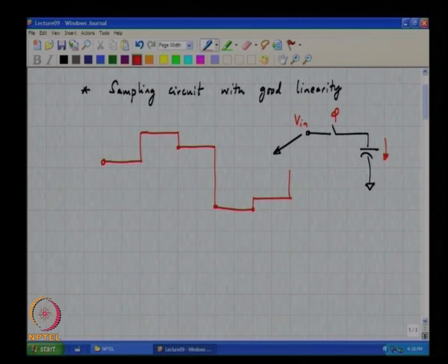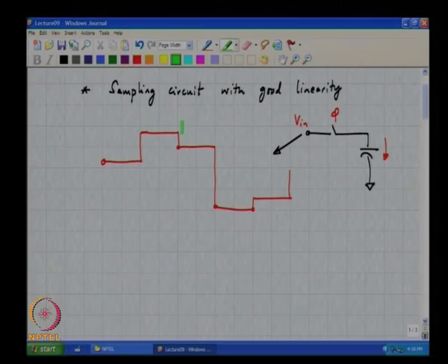Is this clear? Of course, when the input changes at the end of the clock period, there is a big difference between the voltage to the left of the switch and the right of the switch, because the capacitor will not allow the voltage to change instantaneously. So there will be a spike of current that occurs, however that will only occur around transitions of the input and will quickly die down, right, as the cycle continues.